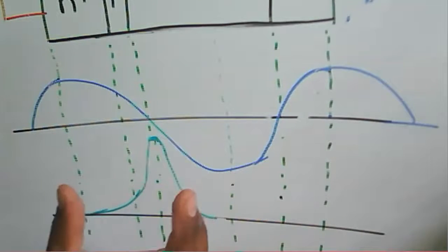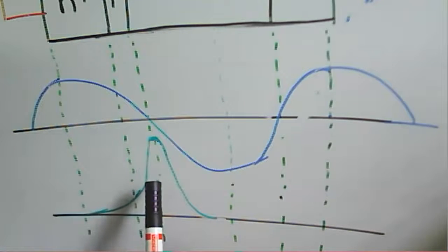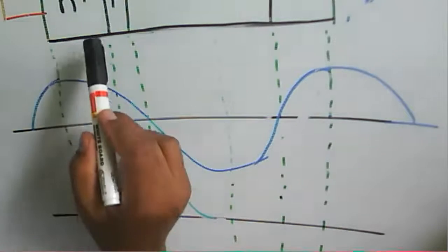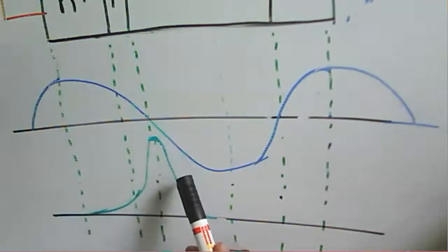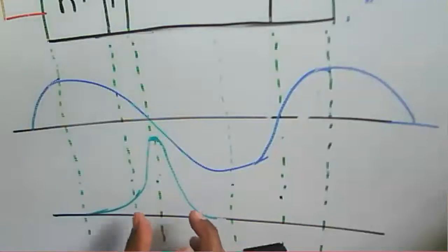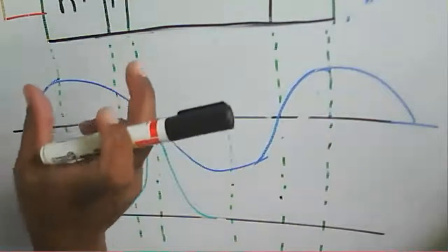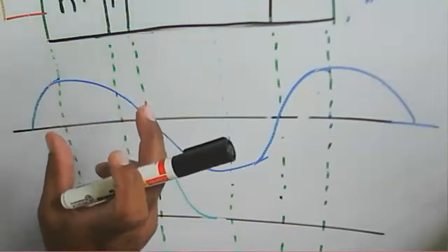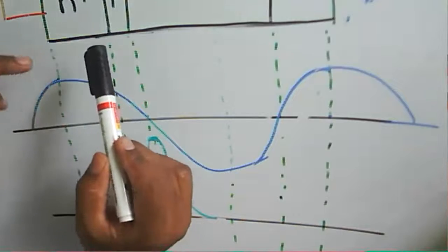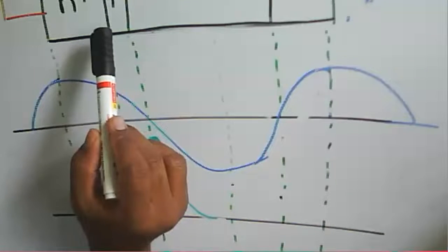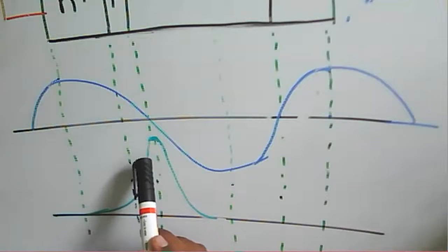And then the carrier current at this junction, if you see, looks like a pulse at this N plus P junction. That pulse is of a very short duration, because this is the avalanche region. So the pulse will be of a very short duration, and the maximum number of carriers is generated here. That's why the current will be maximum at this particular region.